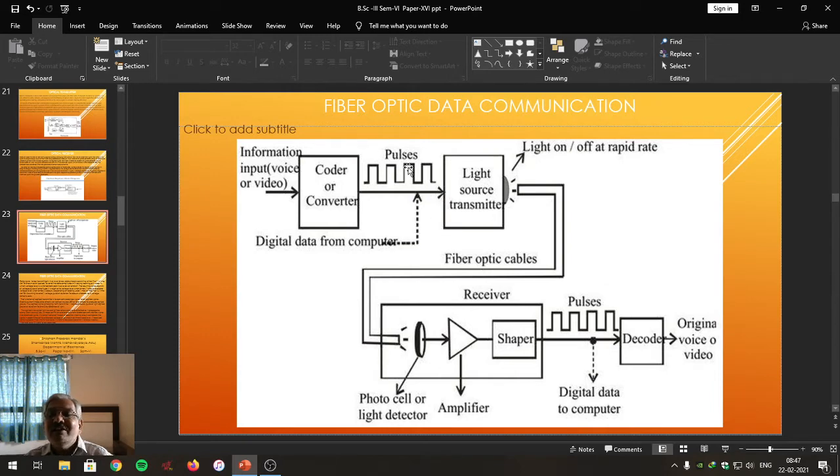This digital signal, which is going to vary between the two voltage levels, is transmitted by using amplitude shift keying technique. Basically, digital data is a two level varying signal. One is a minimum level, that is 0 volt, another one is maximum voltage level, that is we can call it as 1, that is a space and also the mark signal. Such a two level signal we can call as a digital signal. Whenever this digital signal is to be communicated through the optical fiber, amplitude shift keying technique is used.